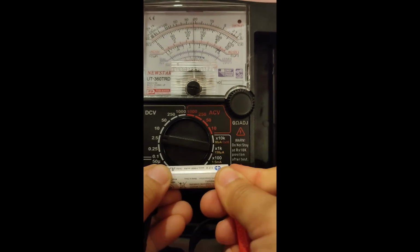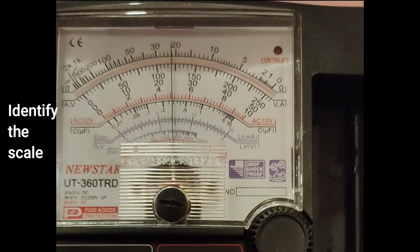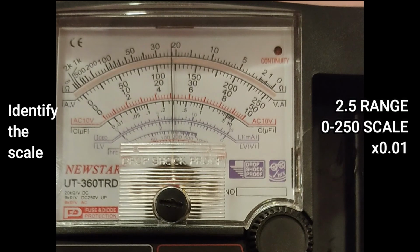Then, read the scale. In reading the scale, if we use the range of 2.5, we are going to read the scale of 0 to 250, and the scale reading will be multiplied by 0.01. We now read the scale.